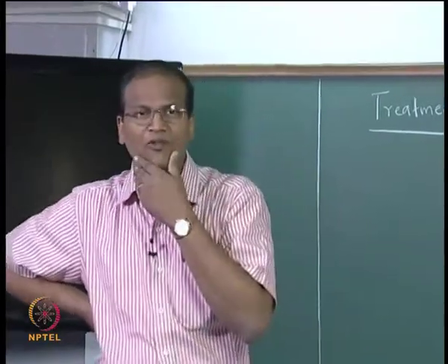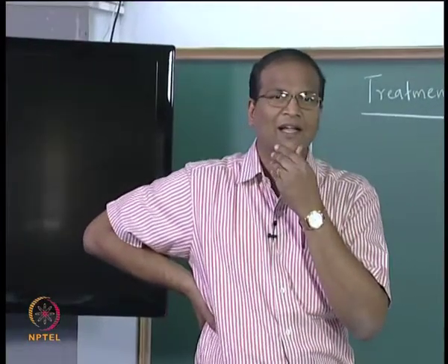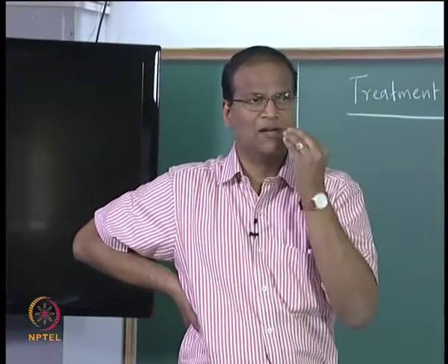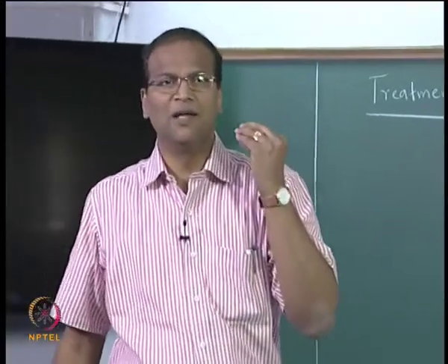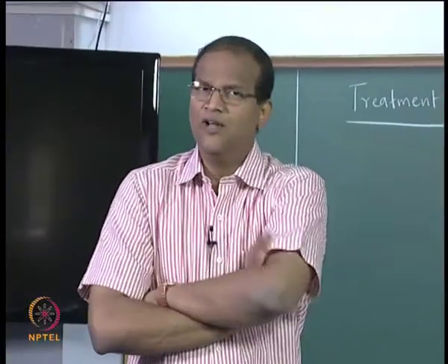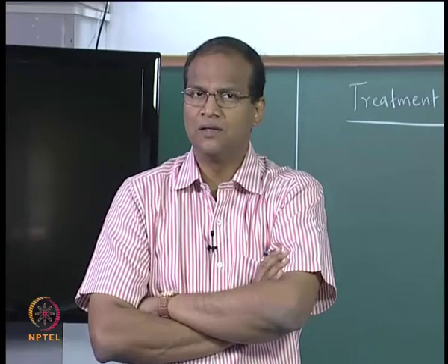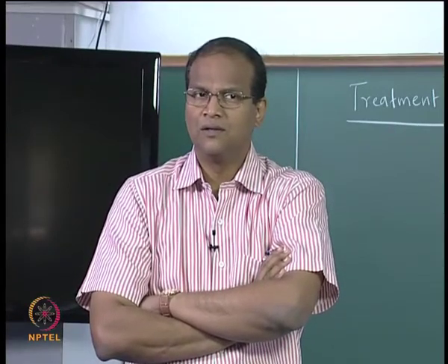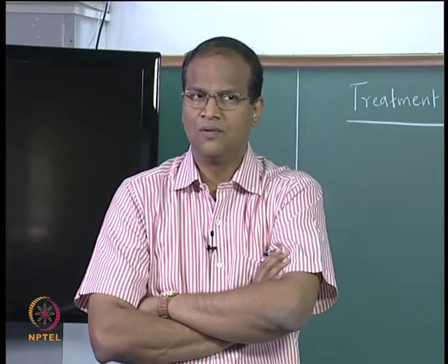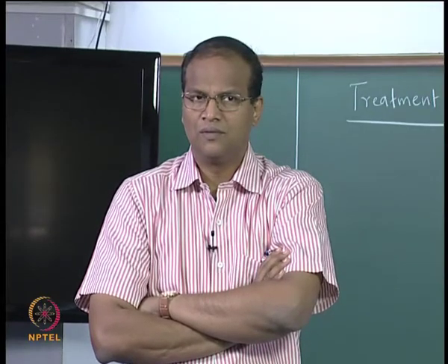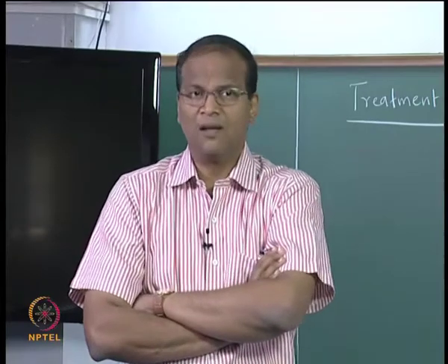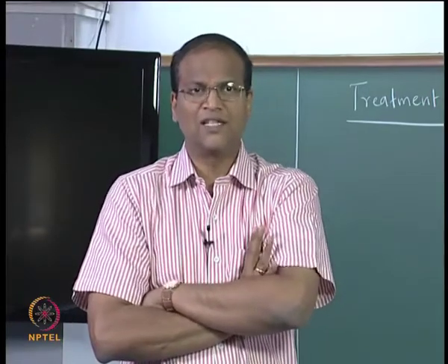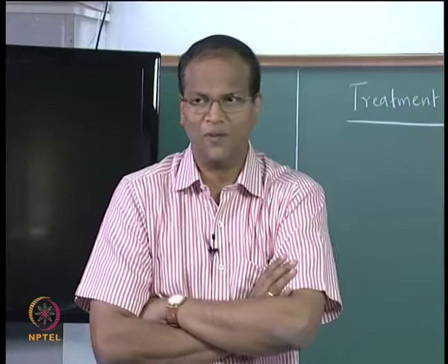Now for a moment if you pause and think, if you cannot use that epsilon sigma T to the power of 4 because epsilon lambda is a function of lambda, how do you think the formulation will get changed? Epsilon lambda is a function of lambda, so I just cannot use epsilon sigma T to the power of 4 and have one radiosity.